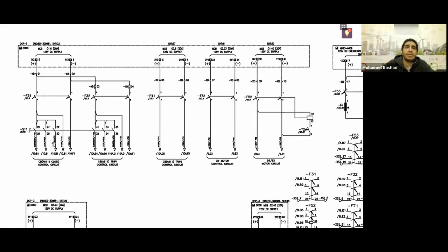And what about the remote, Engineer? The remote was used in the past. Now, from the control room, you go to the RTU, then to the SCADA. The SCADA used to send it to you, but now instead of the control room, there's just a computer. The whole idea is that all these PCUs are IED devices connected via fiber optic to a set of switches. In the end, all these switches output through one fiber optic and another redundantly connecting to an industrial PC, which is your case.